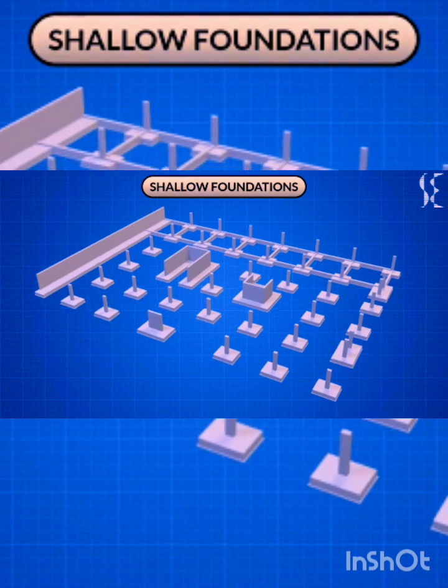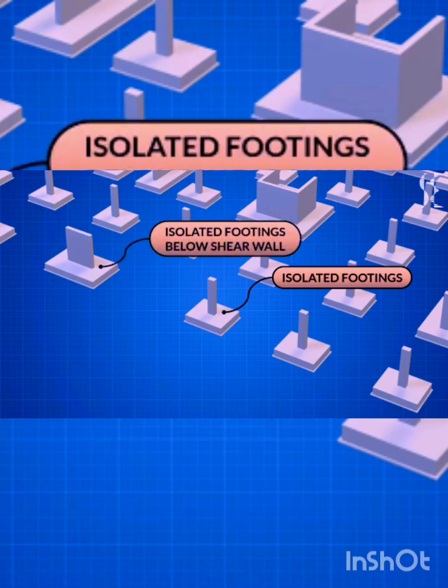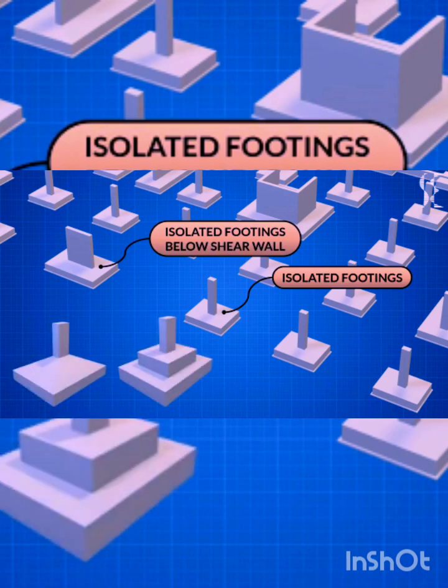First is isolated footings, which are provided under each column individually. They can be just a uniform thickness reinforced concrete pads and can be square, rectangular, or circular in plan as per design and analysis requirements. They can also be provided below individual shear wall. Isolated footings can be sloped or in steps as per design or construction requirements.